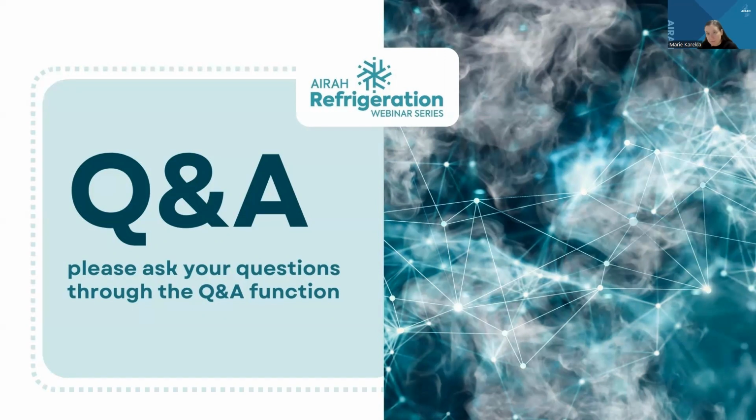Generally, we do have isolators for fans in the room, but that is site specific. It depends on the electrical installation and where the switchboards are located and the like. There's no regulation as such, really. It depends on the client's requirement. From a safety point of view, I would recommend putting an isolator on your fan for people to work on. Yeah, sure.